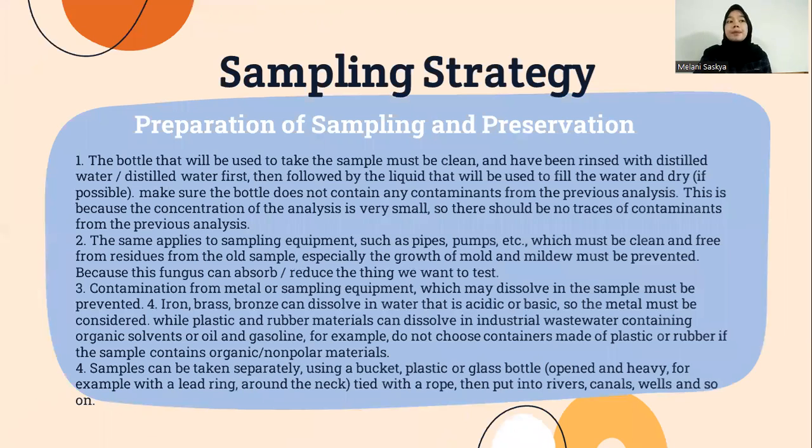Now, preparation of sampling. The bottle that will be used to take the sample must be clean and have been rinsed with disinfected water first, then followed by the liquid that will be used to fill it, and dry, if possible. Make sure the bottle does not contain any contaminants from the previous analysis.